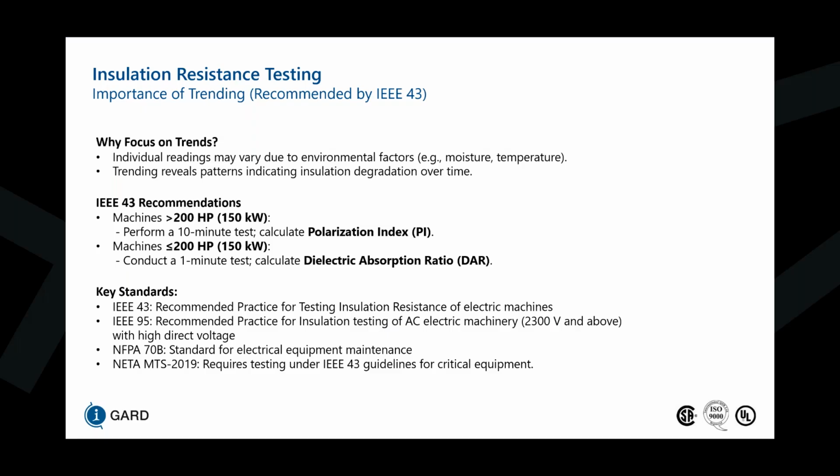For machines that are below or equal to 200 horsepower, you can conduct a 1-minute test and compare the 60-second insulation resistance readout over the 30-second insulation resistance readout to get a ratio called the Dielectric Absorption Ratio, or DAR.